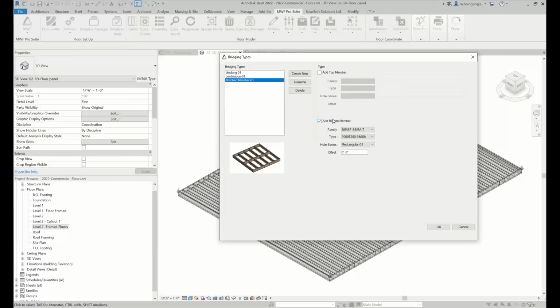Next one is our notching member. For this one here, I'm going to put a notching on the bottom of my panel. So you can see in the little image that we're given, it's just going to be a member. I am going to be using a T member, and since I'm using a T member, I need to create notches for our joist so the joist can sit on it.